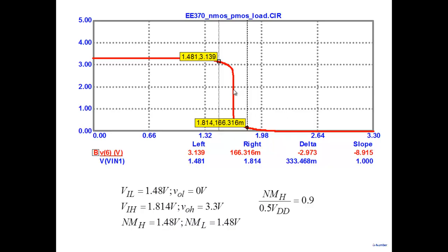Now, the issue is if I want to shift it towards the right, how do I do it? So, which means effectively what it means is inverter threshold voltage you have to shift to the right. Inverter threshold voltage decides how symmetrical it is. So right now, inverter threshold voltage is 1.65. If you want to shift it by, let's say, VIL, you want to make it 1.68.